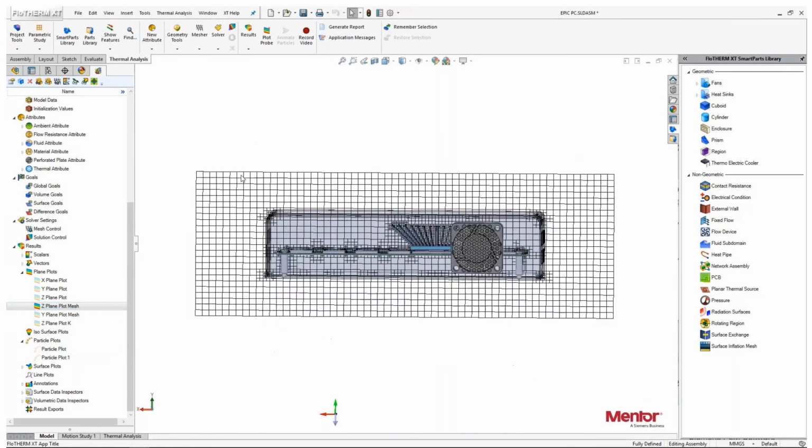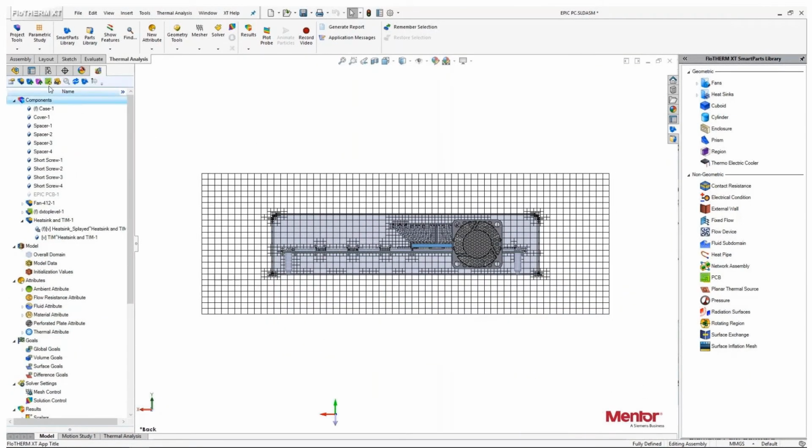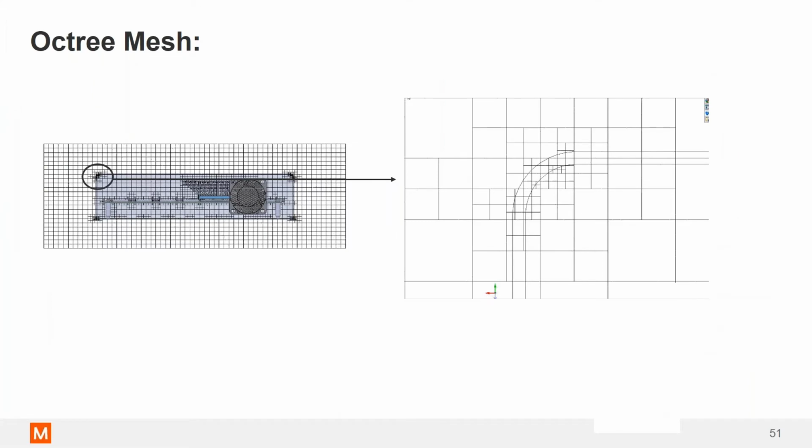All right, so let's look at the mesh in a lot more detail and know some of the features. So zoomed in near the corner over here near the fillet, you can see that we have a greater number of cells in this case. So for example, we have the base mesh over here, and this cell is split up into basically 4 in 2D, or rather 8 in 3D. And then again, this cell is split up into 4, and then so on. So this level of transition can be done up to 9 levels of refinement to create exponentially smaller cells.